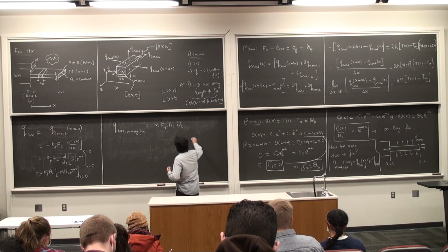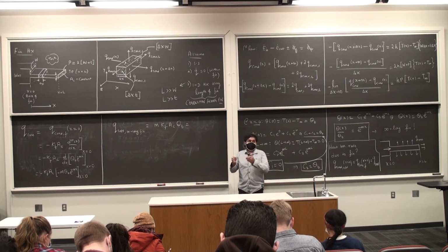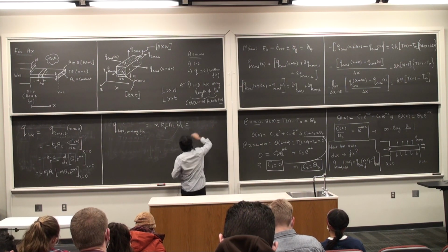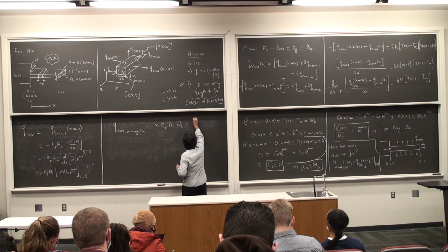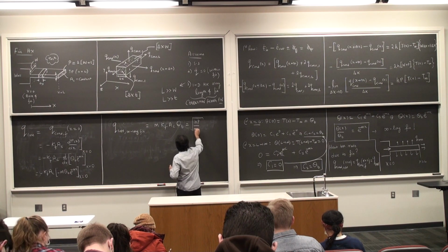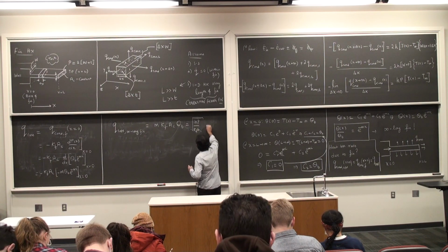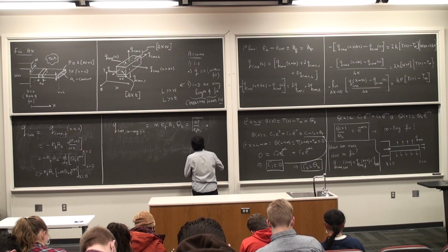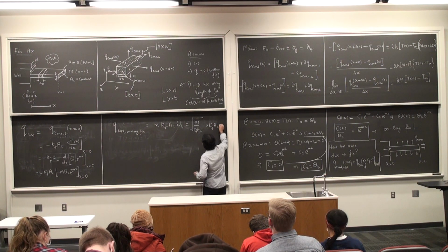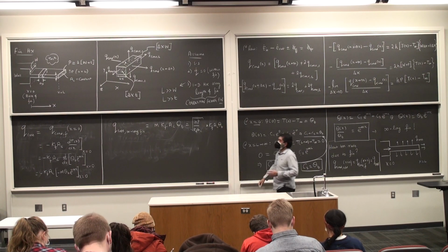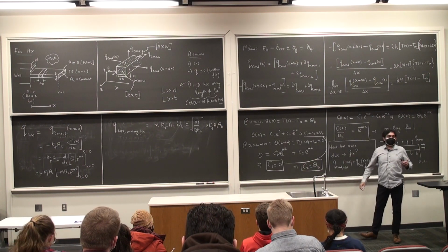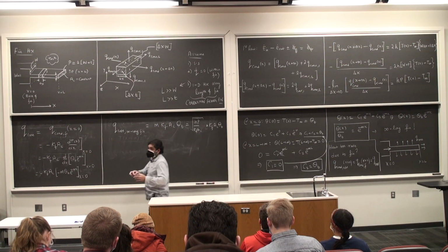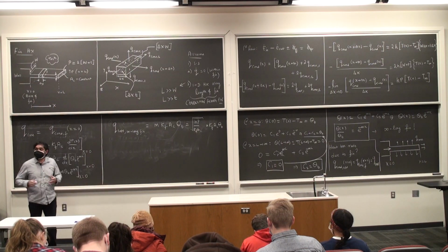m is defined previously. We had defined m square as hP by kf times Ac, so m is the square root of hP by kf Ac, times kf Ac theta b. I have a square root of kf times Ac in the denominator. I have something of the same ilk on the numerator without the square root. I can rearrange all of these things and write a very nice nifty equation.